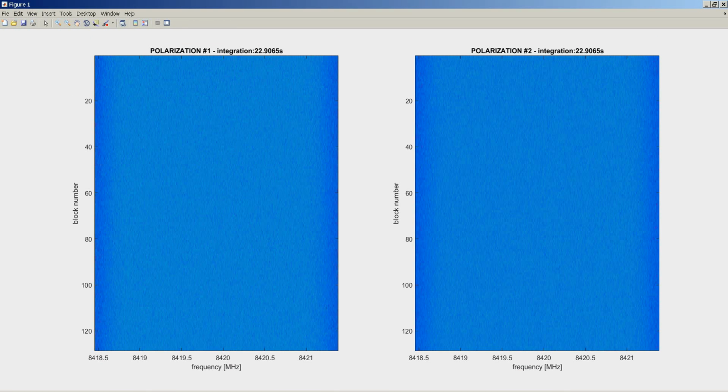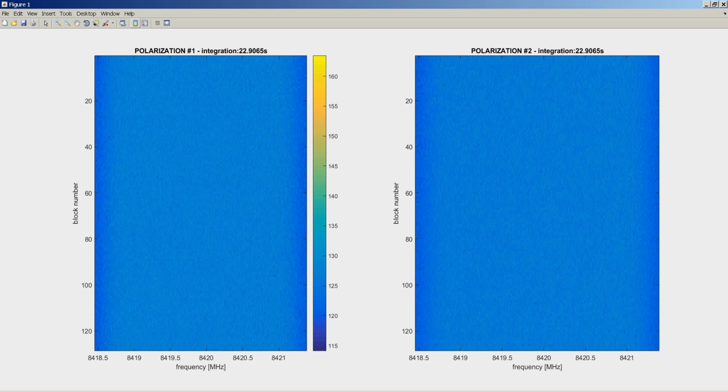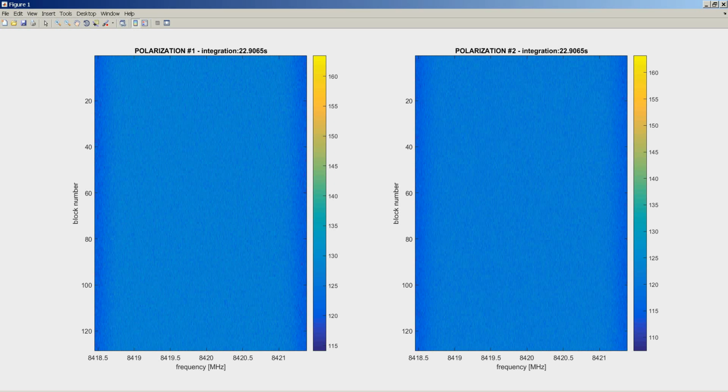It seems like a pretty empty waterfall plot, unfortunately. But the reason why it looks so empty is that the frequency resolution that I asked for is pretty big. So it has this advantage of reducing the noise level, the power spectral density of the noise, because it's averaged over lots of frequency samples. But those frequency samples are so thin that you might not, at first glance, see the features of the signal that you're expecting. So once again, I know the frequency of my signal, and I like to zoom in.